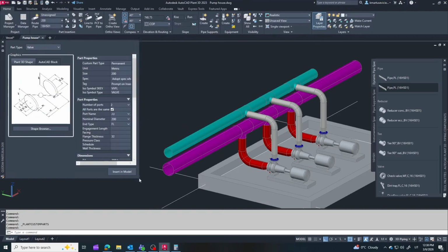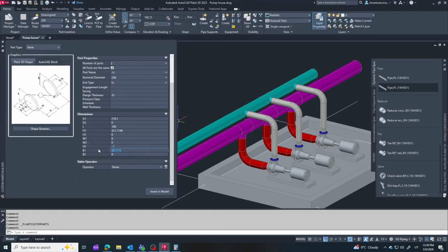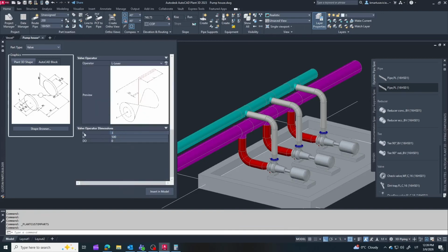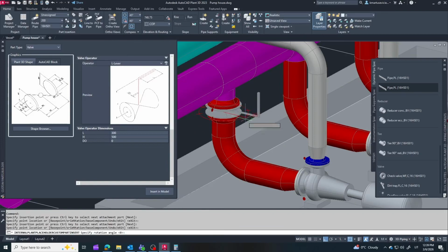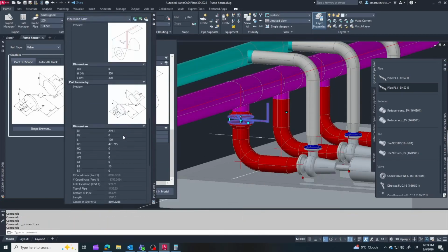First, I install valves to isolate the manifolds from the pumps for maintenance purposes. For this, I selected widely used butterfly valves. When placing the valves, you also need to check that the valve disc has enough space to open. It should not collide with nearby components, for example the disc of a check valve or other internal parts.